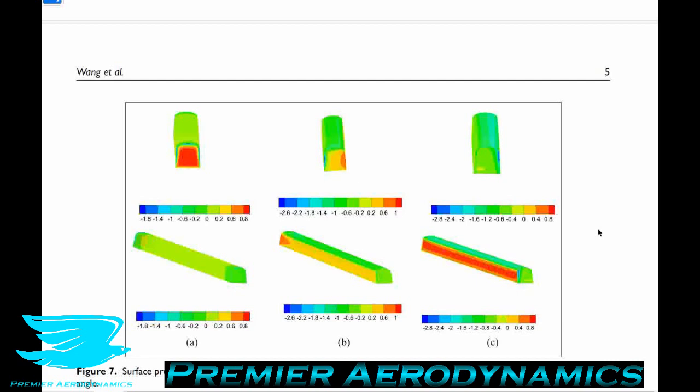But as soon as we go to like 60 degrees or higher, we then start to see differences with different train noses. And that tells us that we need a sleeker train nose to maximize the lift coefficient. And if we want to reduce the lift coefficient, make the train blunter at the front with different yaw angles. The problem with that is if we have a blunter train nose, generally speaking, we will get a higher drag. So that's the trade-off there.